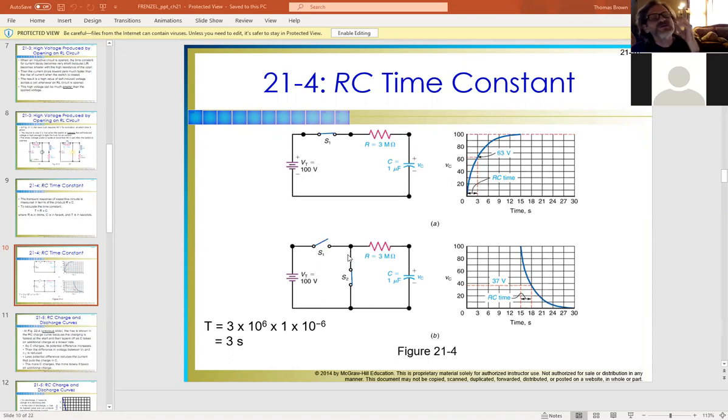Otherwise, the unique thing about a capacitor is you charge them up, you can literally disconnect them from the circuit, and they will hold the charge for a good time. I've had power supplies when I used to work in a repair center, and you have to be careful with those because some of them have 400-volt capacitors on them, and they will still be fully charged. They've been disconnected from the machines they were in, packaged up, put on a truck, shipped out to us, sat somewhere in receiving, okay?